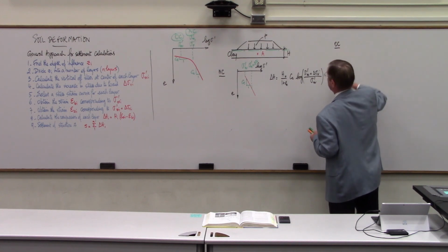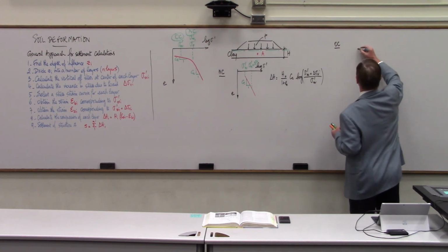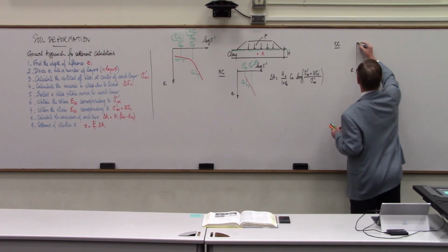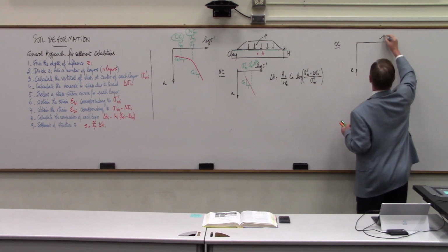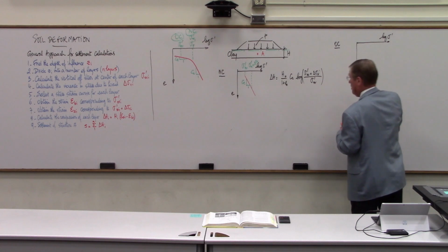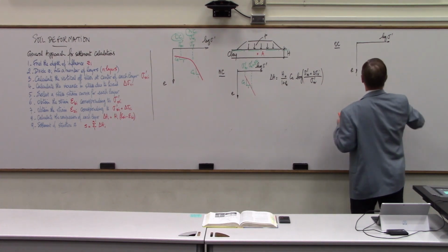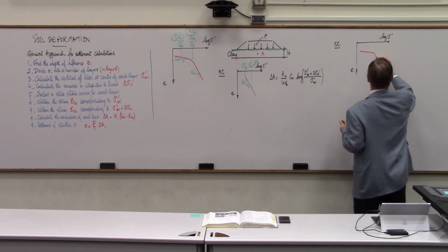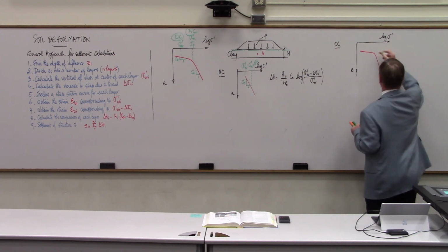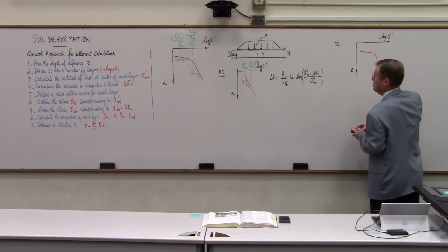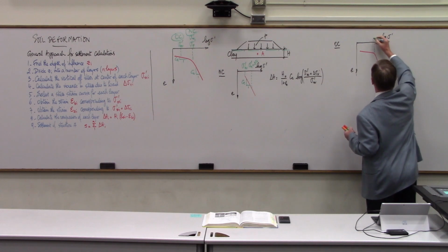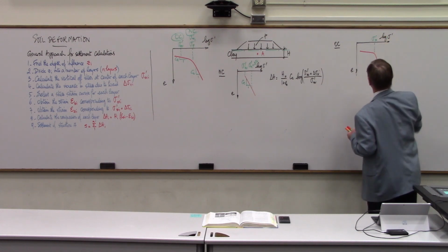If the material is over-consolidated, then the curve looks like this. We have void ratio here, and we have log of sigma prime. But the curve has two parts prior to the pre-consolidation value, and I exaggerate a little bit the knee there, and then right here is the pre-consolidation value, sigma prime p.